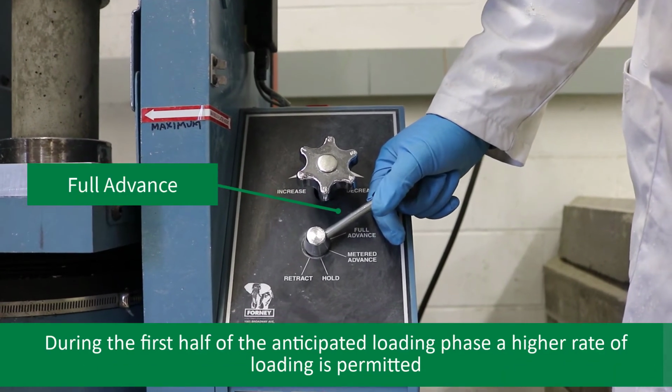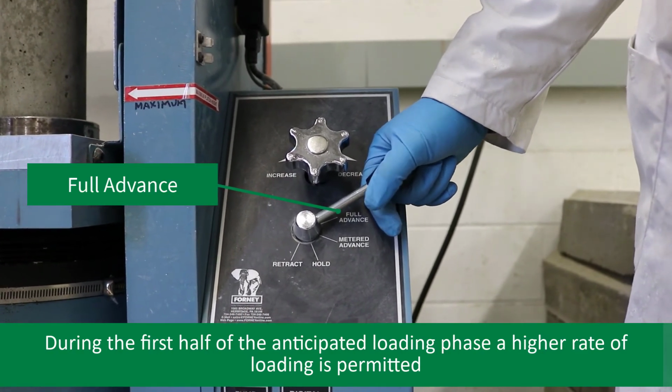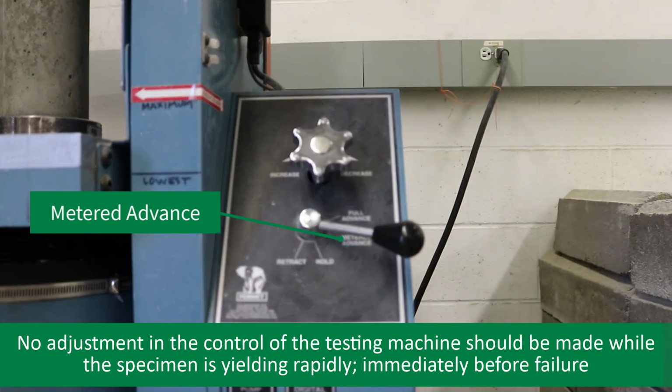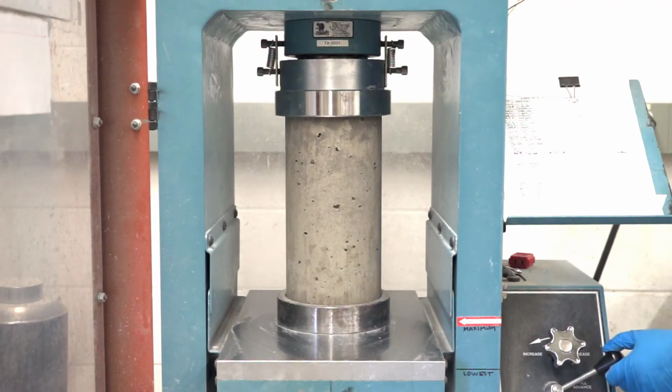During the first half of the anticipated loading phase, a higher rate of loading is permitted. No adjustment in the control of the testing machine should be made while the specimen is yielding rapidly immediately before failure. Continue applying the load until the specimen fails.